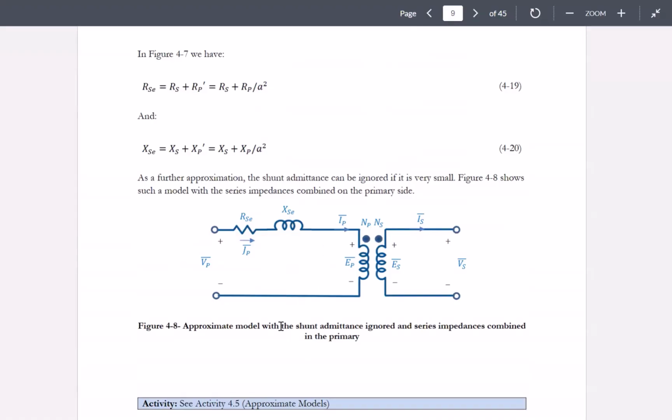So what we do is apply a short circuit here, short these two terminals, and then put a varying voltage source here, and start to increase the voltage from 0 all the way up to when you see the rated current flowing through the primary circuit. You don't want to put a large voltage here, because you will damage your transformer since it's shorted. You just want to increase the voltage on the primary side until you reach the rated current.